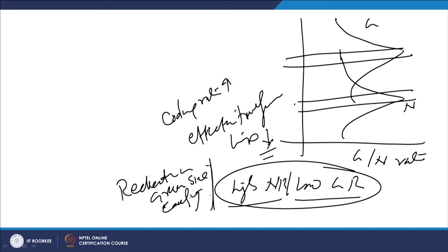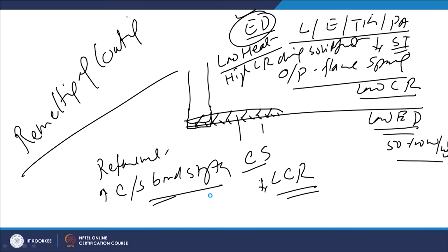So, apart from the refinement of the grain structure, if there are impurities present in the form of inclusions here and there, remelting of the coating will lead to the floating and elimination of these pores and inclusions up to the surface.